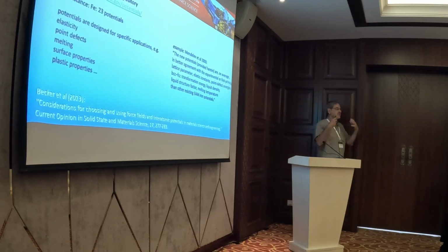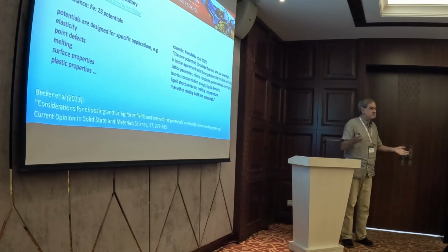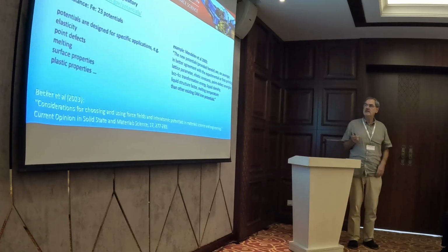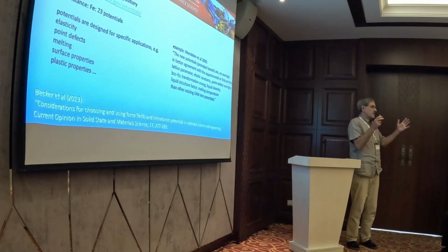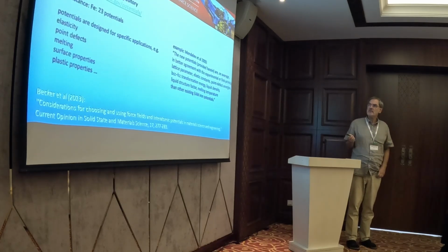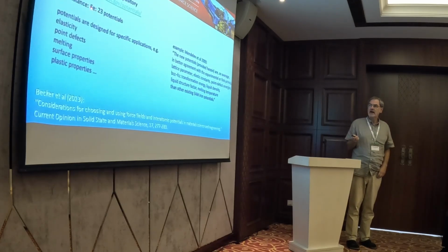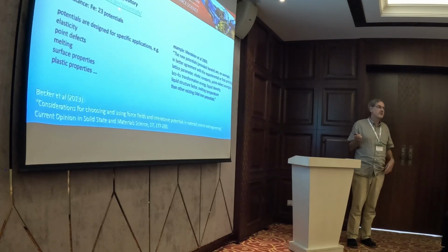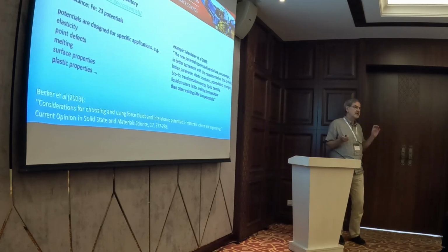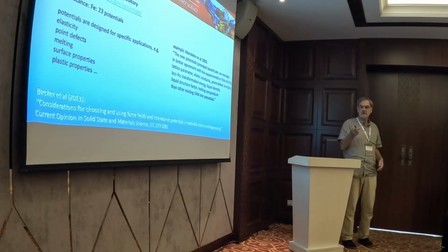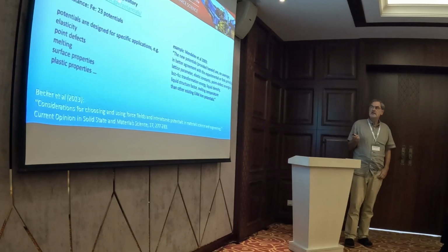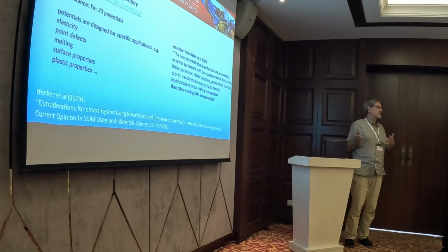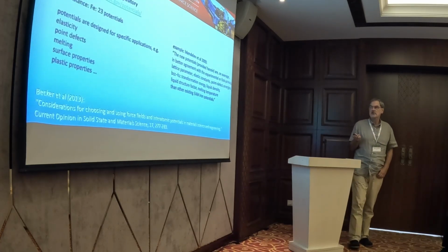So this means now since 40 years or so we have, let's say, valid or reliable potentials for large classes of materials, also for metals. If you now look into which potential to choose for your problem, let's take an example. Let's look at iron. Iron is an important metal. If you want to describe an iron surface, you go to one of these repositories where you find which potentials are available, and it shows you now there are 23 potentials in this repository. I mean, there are more around, but they did not yet go into this repository. This is the repository built by NIST, the American Institute of Standards, and it is the repository used for LAMMPS, so they are all available for LAMMPS. You can just choose what you want.